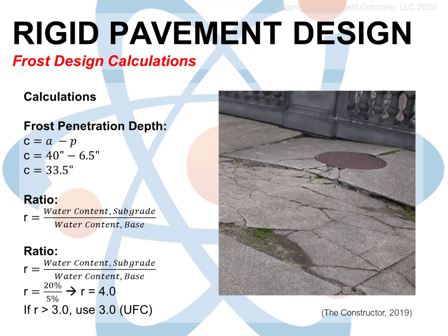Relative to the visual aid on the graphic, what has probably happened here is that there was a leak in the piping associated with this manhole, putting a lot of water into the ground around and under the manhole and its associated main line. As freezing occurred, the steel lid and concrete transmitted the freezing temperatures down deep, causing the water to freeze and push the manhole and part of the main up out of the ground.